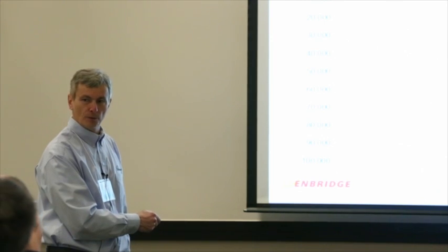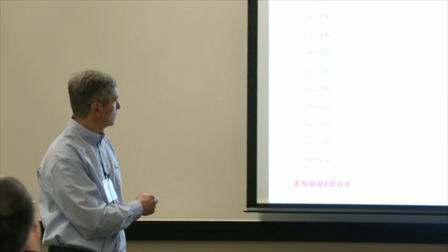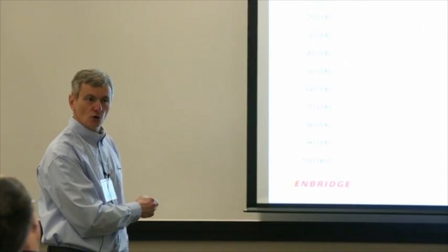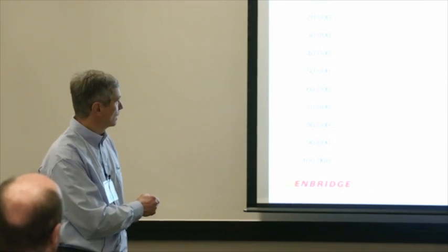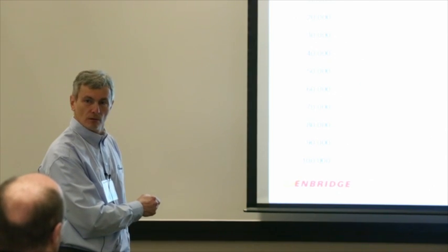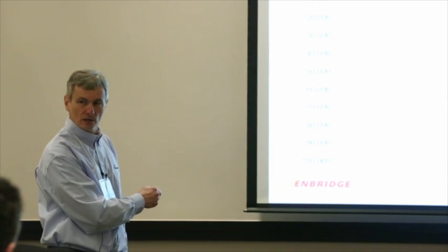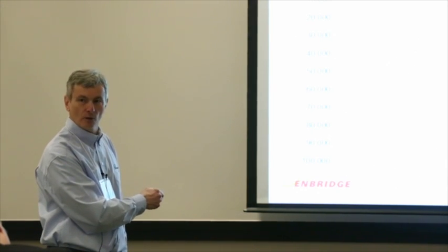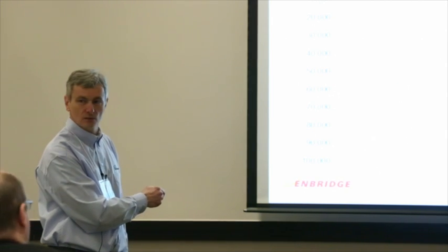But if you're doing small operational changes, if you don't have money this year for capital projects, this will be a very small line here. Go and change all your filters, make sure that all the valves are in the proper setting, and you will get change here. And if you keep a log over here of what you've done on which date, you can go back and say, oh, changing the filters did this. Now I can quantify. Now I can say, I have to change the filters. They're expensive, but it's worth my while changing them every 6 months because this is what I gain.